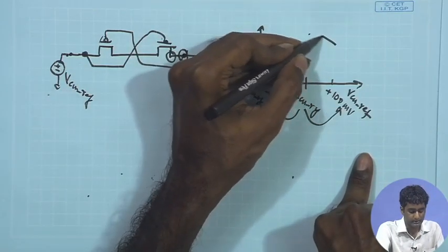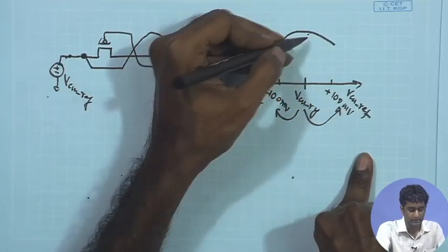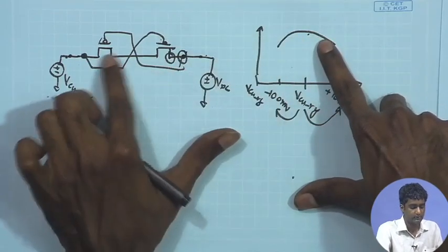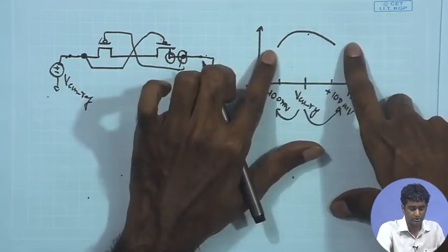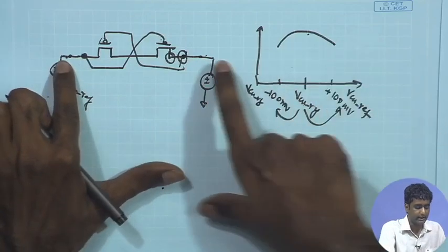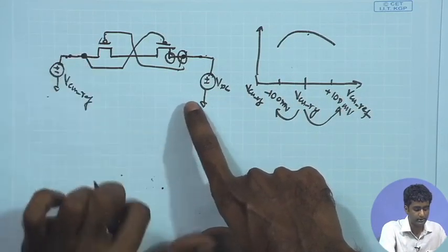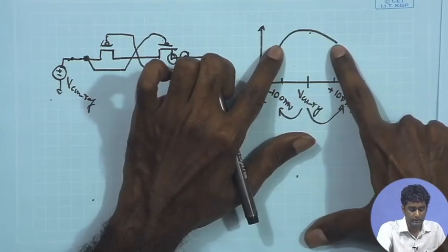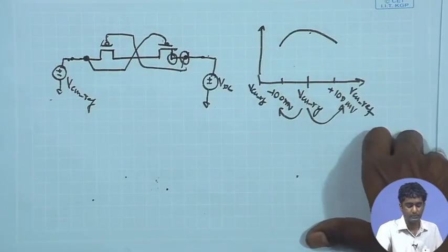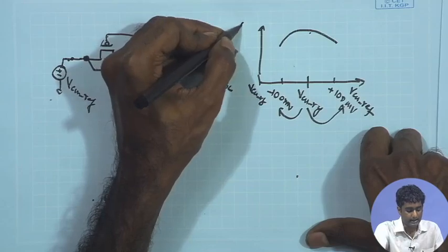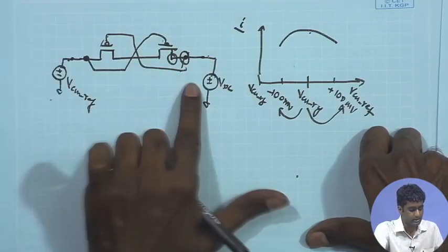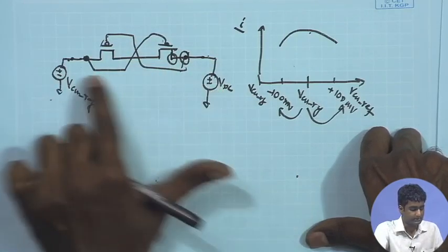So, the impedance characteristics may look like something like this. For smaller differences, it gives you a high impedance, but as the potential difference increases because of increasing leakage components, say the leakage component between gate and bulk and the gate and the junctions, it will lead to reducing impedance. So, that is what we expect. If you plot the I divided by delta V, that is the V DC minus V ref.